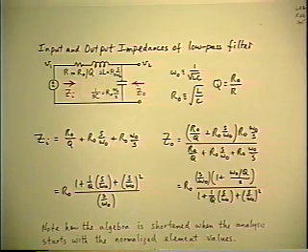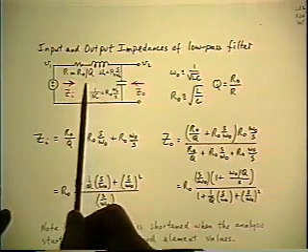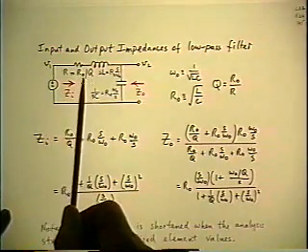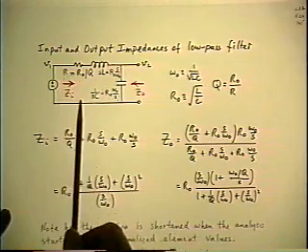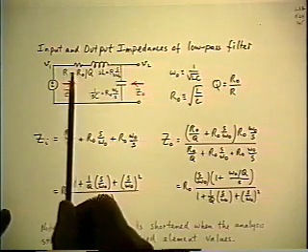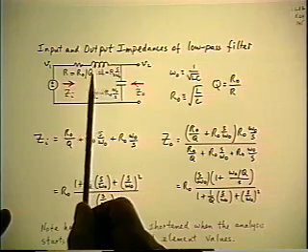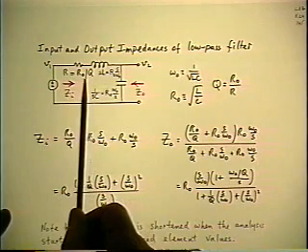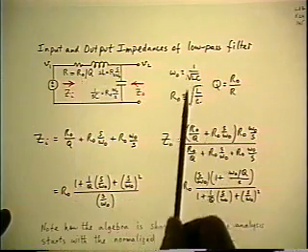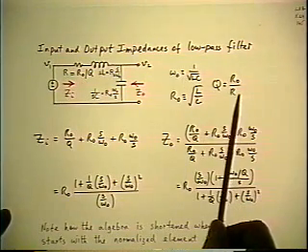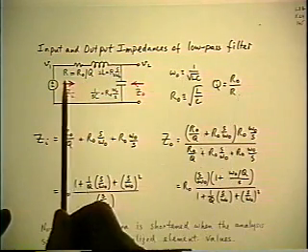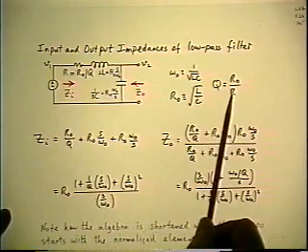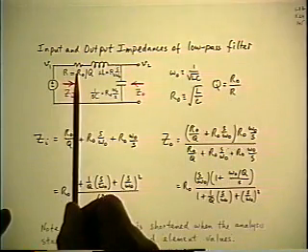Get them in right at the start. Then you don't have to go through that substitution again when you already know what you want the result to be in. So the way to save some work here is the next time you want to calculate something to do with this circuit, replace the original circuit elements in terms of the quantities you want in the result, which you do simply by inverting the definitions of those quantities. So, for example, instead of writing R, we invert this one and write R0 over Q.